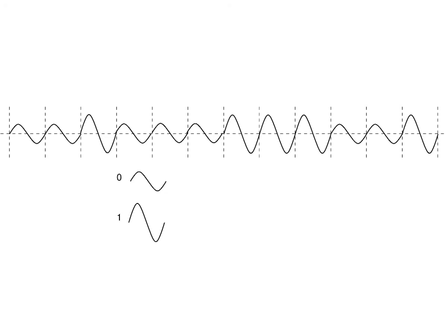What are the first 3 bits? First 3 bits are 001, okay, and I think you should be able to work out, okay, low, low, high, low, low, low, high, high, high, and so on. So simple mapping: over this duration, measure the amplitude. And by the definition, we said low amplitude bit 0, high bit 1. It can be different, okay, but we need to have this mapping defined between the signal element and the bit.